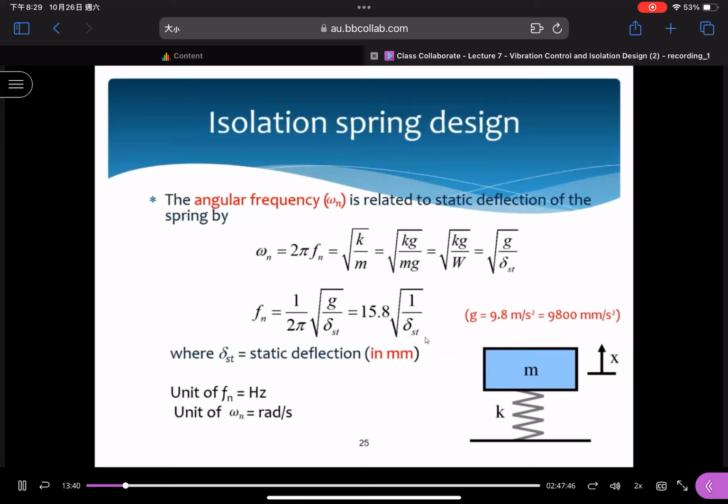The first one is exercise 2A. In this example, both springs are connected in parallel. You can see that the final result for the angular frequency is 14.14 radians per second. And for the second question, even if the stiffness values are the same, if the connection configurations are different, you can see that the result is totally different. So please pay attention to the connections. And I already showed this one to you.